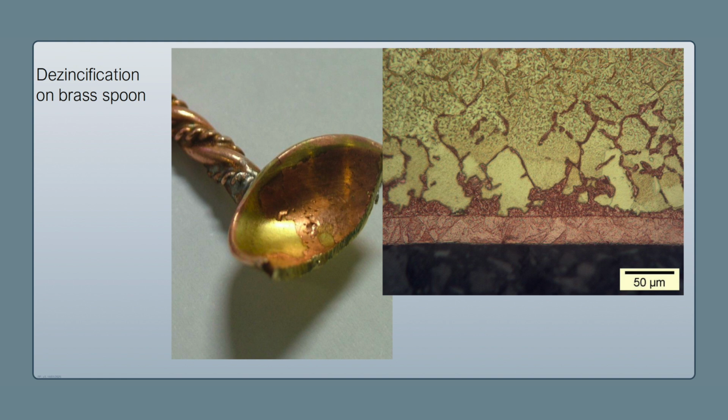This sort of corrosion, although it's not that relevant here, does result in poor mechanical properties. For plumbing fittings and pipes, they would often use brass because it's a little bit stronger than copper itself. But they have developed DZR brass and other dealloying resistant materials for those fittings.